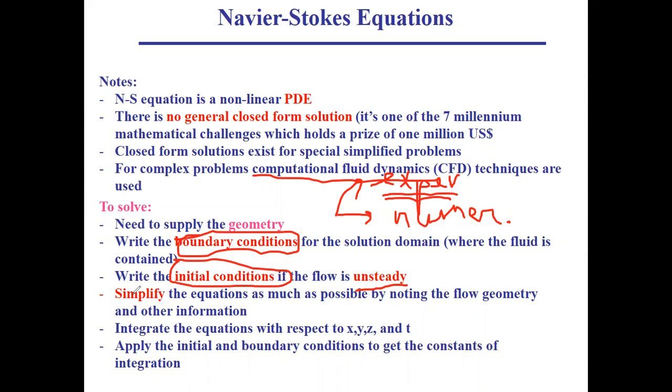In the literature we say that if we have a gradient in temperature within the space smaller than 10 degrees, so if I don't have a large variation in temperature between the surfaces of my space, I can neglect radiation. So this will simplify the energy balance a lot. So you can try to do simplifications that will not affect your results a lot, so you can reach an accurate solution in a shorter time.